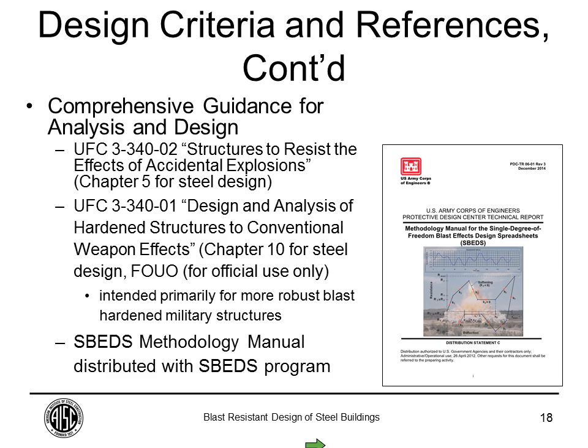If you're looking for more comprehensive guidance and just want to dig really deep into the technical information, as far as how the equations were derived and the testing that went behind some of the approaches that we have right now, you probably want to go to the UFC 3-340-02 or 3-340-01. I think those are the most comprehensive set of documents that we have in terms of providing blast resistant education and knowledge behind the procedures that we have today. I think the SS methodology manual, which we have right here on the right, is a good balance between having enough detail to explain why things are the way they are without being overwhelming.